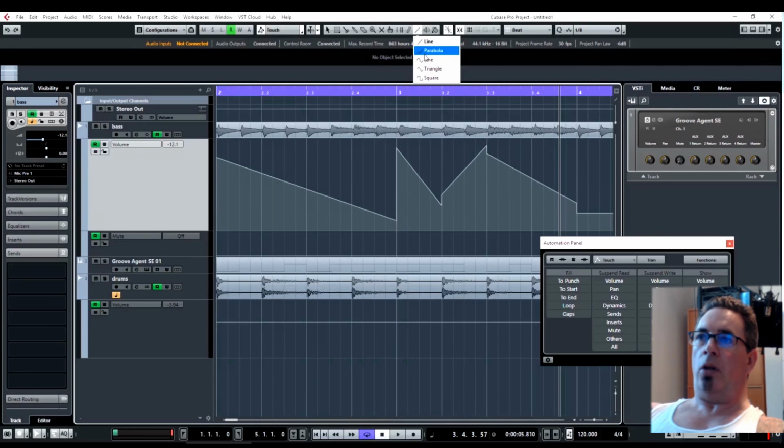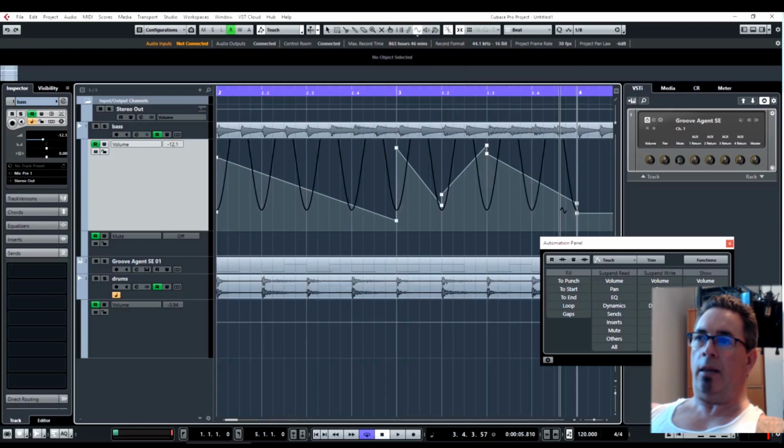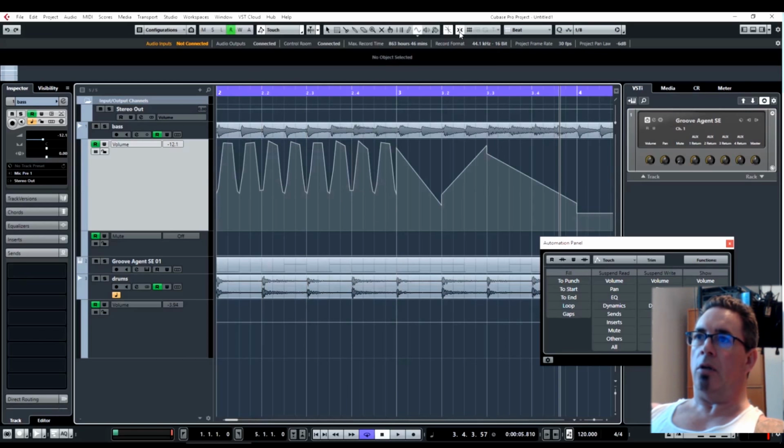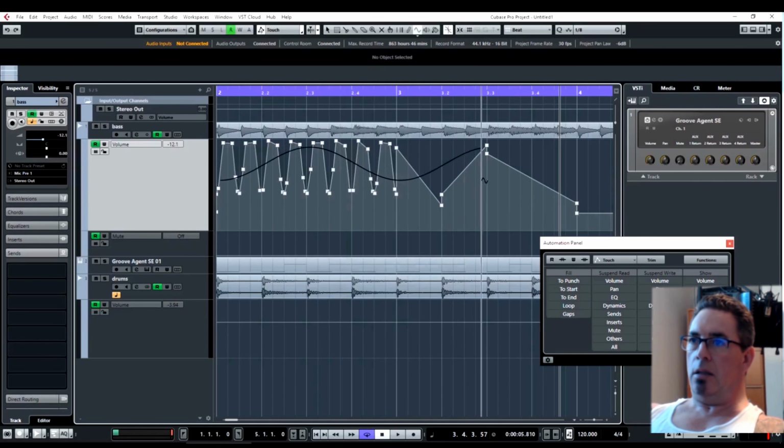That is useful. The sine wave tool is basically like the parabola, except a full wavelength. If you hold down Shift and then drag your mouse, you can actually affect the frequency. And that I believe is also affected by snap. So turn snap off and do the same thing, holding down Shift.